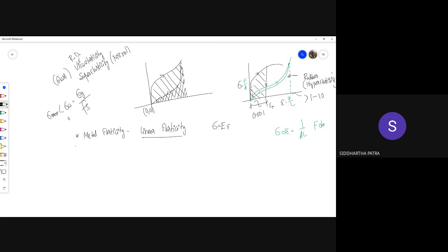Now you see this wave of paranoia in this expression, where we are not designing components up to yield stress. We are not going past yield stress by no means. Then we are dividing that by a factor of safety to get a working stress, and even the maximum stress in our system we want to keep below this value. So this is one way of designing components.